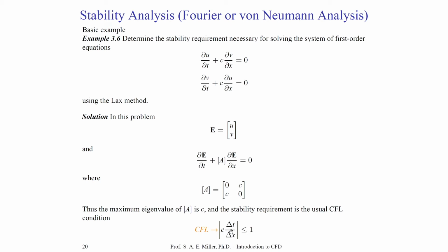Here, we can always calculate the CFL number of the scheme. You see in this case, a CFL number of less than or equal to 1 will be stable. If we choose a CFL number greater than 1, it will be unstable. Another way to look at this is, say we're given some c, which is perhaps a very large value, and we have already made a grid.